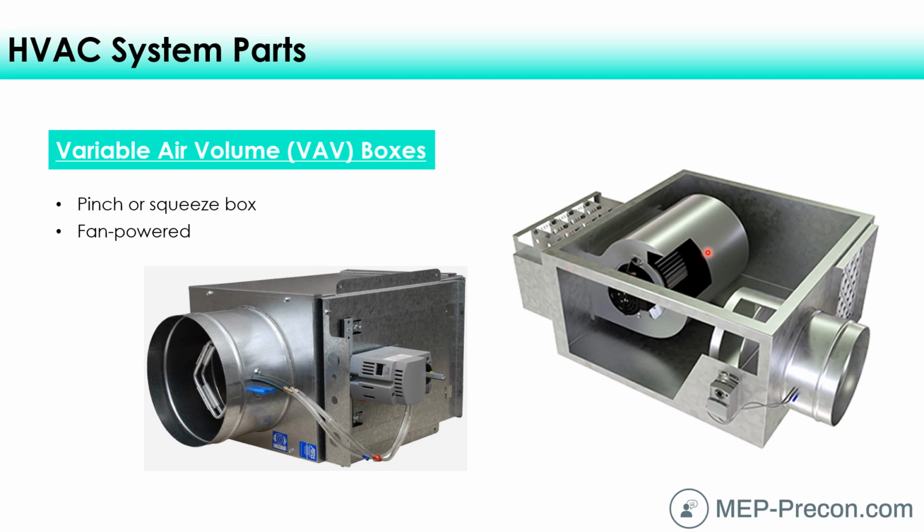And then if it's still not warm enough to satisfy the thermostat, that's when that heater comes on. This fan also provides a means of providing the same amount of air that gets delivered to the diffuser all the time, so that you don't hear a variable amount of air coming out of your diffuser.